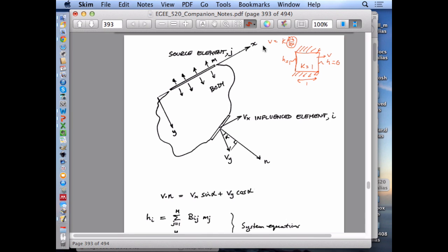And so what we could do is let's try and solve for this, but let's not think of this as being a block that has a no-flow boundary on the top and bottom and is open at the sides, but let's think about it as something that sits in an infinite porous medium.